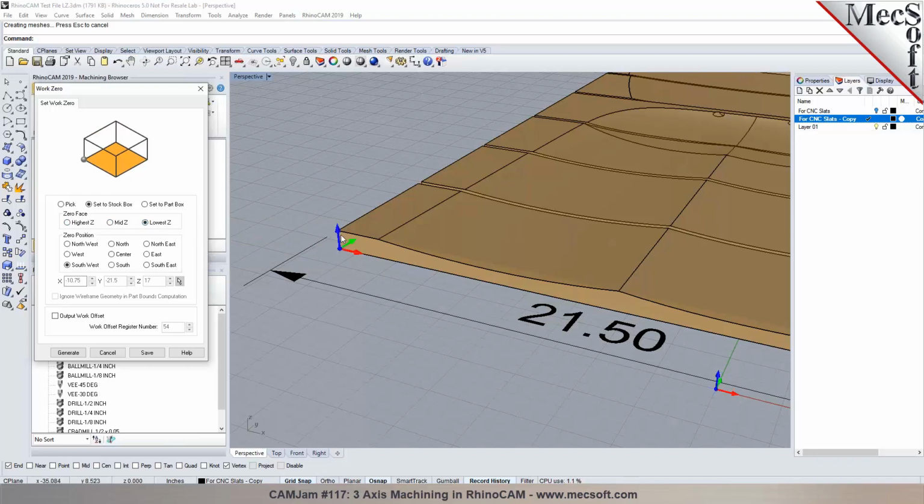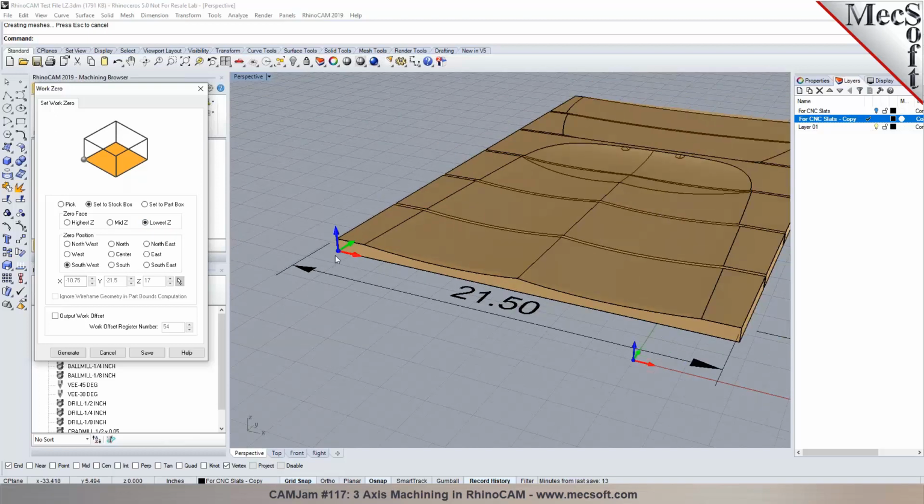Would you prefer doing the touch off at the top of the stock material, or would you prefer the bottom? Since I preserve some top always for when I touch off tools, I do top of the work. Yeah, highest Z. I can do higher Z.